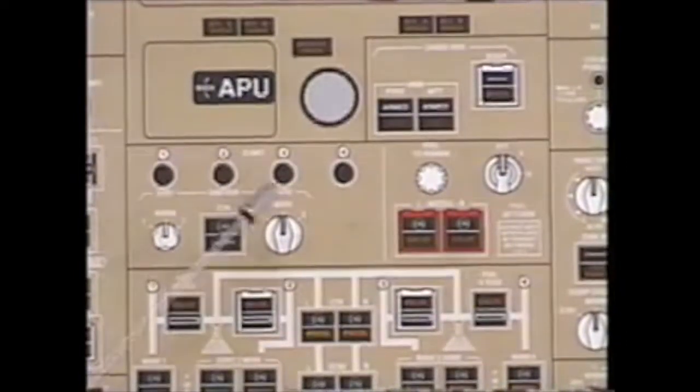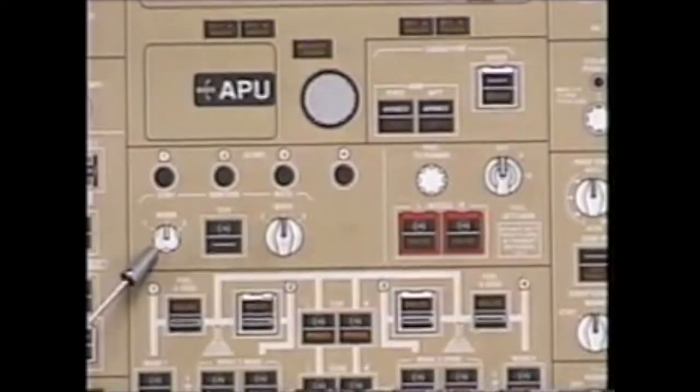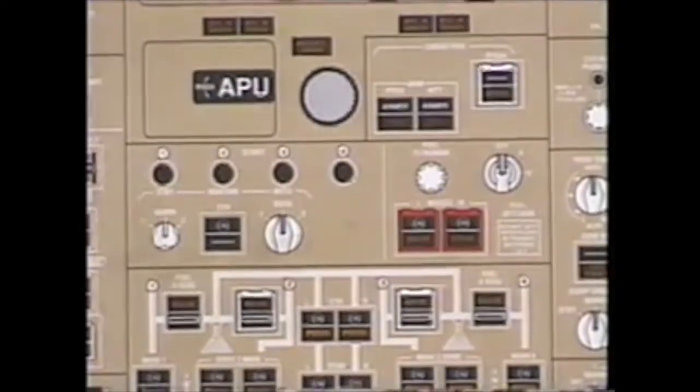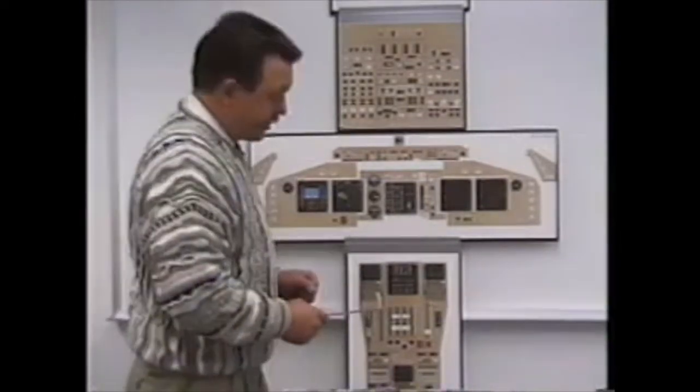Any of the 4 conditions will fire this selected igniter. Standby ignition, normal SOP is to leave this switch in the normal position. In the unlikely event of a loss of all generators, the number 1 igniter on all 4 engines would fire using the backup power supply of DC.